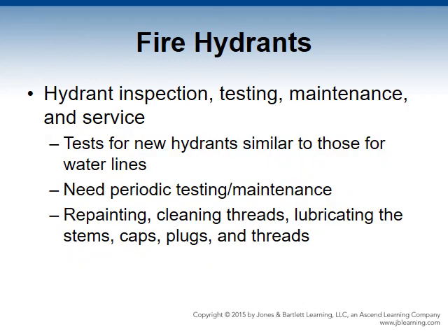Hydrant inspection, testing, maintenance, and service. Just like water supply lines, new fire hydrants require different inspections and tests to ensure they operate as required when needed. The tests for new hydrants are very similar to those for water lines. You have visual inspections of pipe material, bedding material, and securing maintenance. You have hydrostatic pressure tests to ensure there are no leaks. The line must be flushed to get rid of dirt, rocks, and debris that may be inside the pipe and hydrant. They are also flow tested and disinfected to kill bacteria.